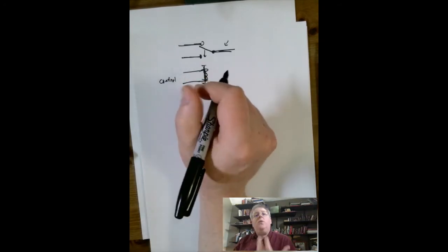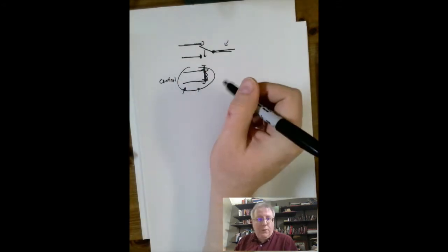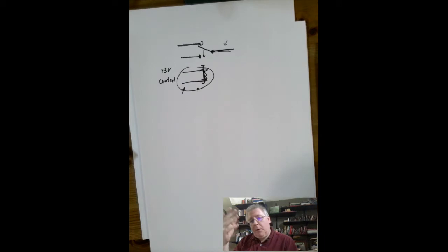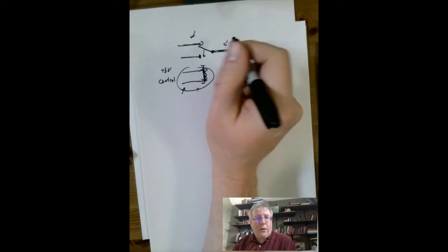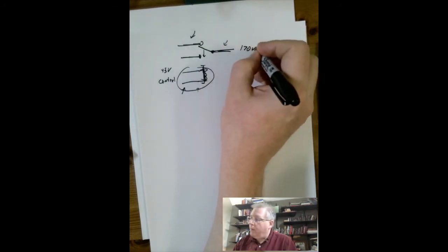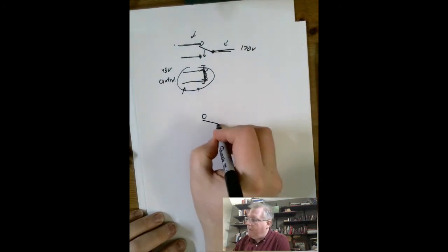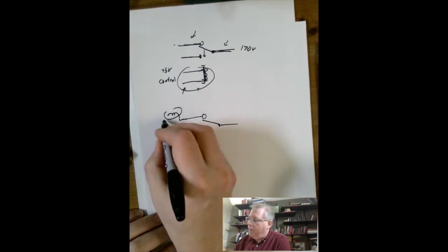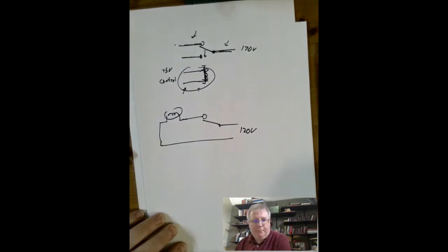So in fact, you might use this if you have like an Arduino or a hobby circuit. So you have a computer that you want to connect to this part of it that will turn the relay on and off. And so this could just be like a plus 5 volt control signal that's coming from a computer. Whereas this can be wall current. This could turn on an electric light or a mixer. And so this could be like 120 volts over here. And so what you would do is you would connect these two things here. That switch would just become part of your circuit, so here's my light bulb or whatever, and then these go to the 120 volt wall supply.